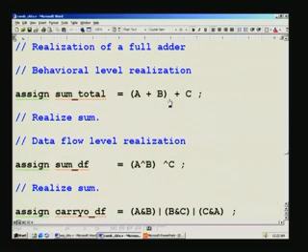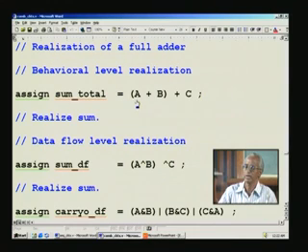We have seen three types of full adders. One is a behavioral level. This is the best because you need to write just a plain addition symbol as such. They are all 1 bit, and you add A and B. There is a bracket I have explained earlier also, to guide the synthesis tool because it cannot make a decision all by itself about what you intend doing.